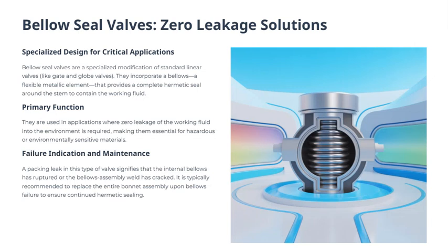When we notice a packing leak in this type of valve, it usually indicates that something's gone wrong internally. Specifically, the internal bellows might have ruptured, or perhaps the weld on the bellows assembly has cracked.